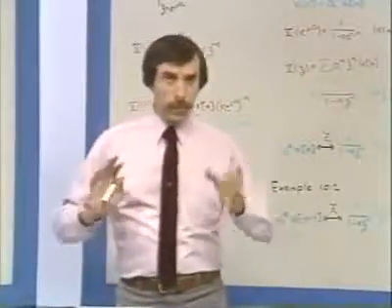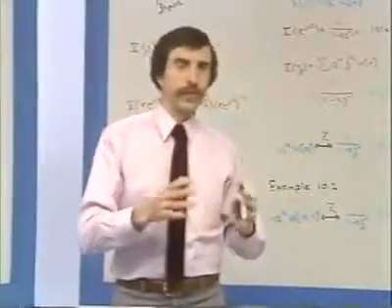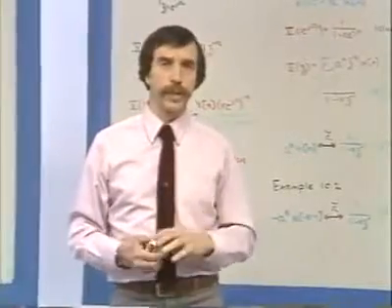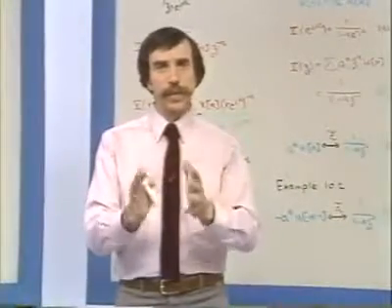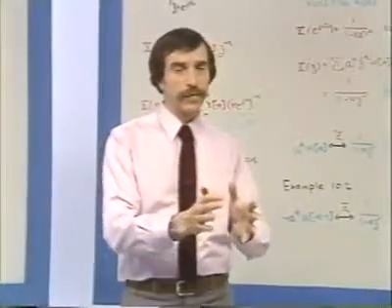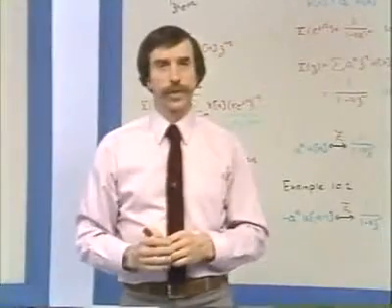All right, so we have one relationship between the Fourier transform and the z transform, namely the fact that for the magnitude of z equal to 1, the z transform reduces to the Fourier transform.